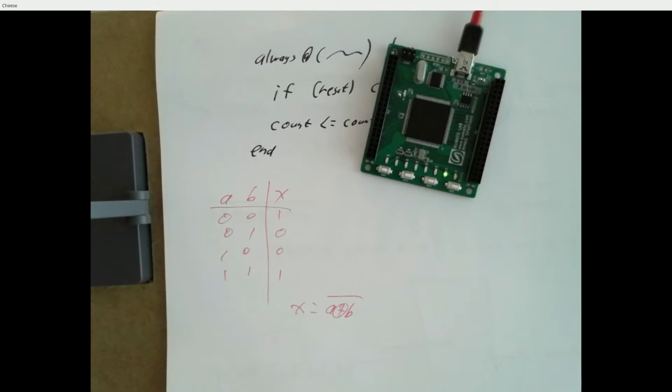So you use an initial and an always statement in the initial block and just toggle a clock every few nanoseconds. But you don't make it count up to 50 million if you're going to simulate it, because you'll have to get 50 million ticks before, right? So you set it to toggle every like 5 or 10 clock ticks instead. So you can simulate it in the Icarus system.